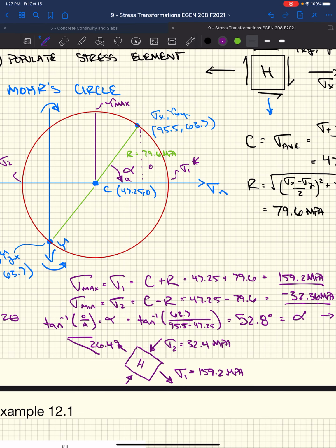So at 26.4 degrees, based on the fact that we're pulling on it now, we're going to get these tensile and compressive stresses. That's why in a drive shaft I showed you some of them buckling. Well, that's because in torsion you actually get tension and compression stresses in that pipe, right? Our drive shaft is essentially made out of a pipe, okay? And pipes can buckle easily, right? So in the compression sense, if the torsion gets significant enough, that means it's going to have significant compression in it, and it'll actually buckle the drive shaft.